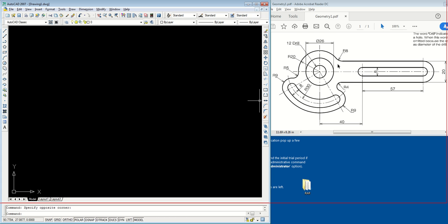After that you complete the arcs whose radius or dimension you can't imagine or accurately calculate. Also, if you have something that is symmetrical, you will usually start from the end or the center line.